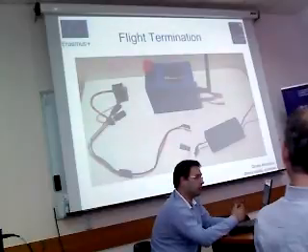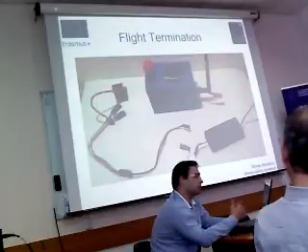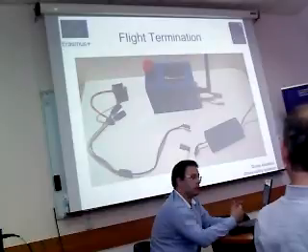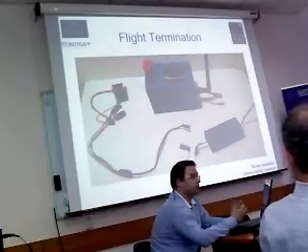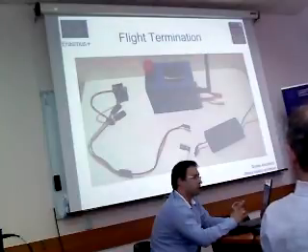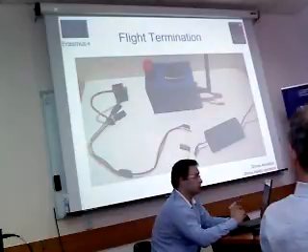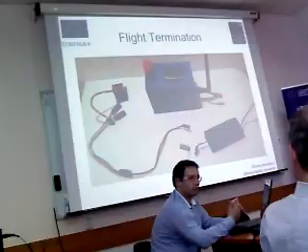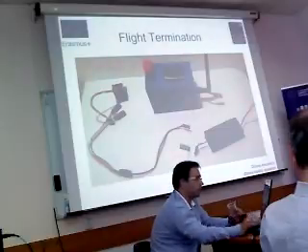Thanks to the flight termination system, if the drone fails within the area of operation, it stops working, thus avoiding a remote control failure causing it to exit the control area and causing risk of personal injury. It immediately terminates the flight.